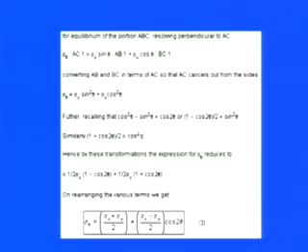Now, within the equilibrium of the triangular part ABC, if we resolve these forces, first we have sigma theta into AC, where AC is the inclined part. So sigma theta into AC into unit depth, that is 1, equals sigma y sin theta into AB into 1, plus sigma x cos theta into BC into 1. Converting AB and BC in terms of AC, AC cancels out from this side, so we can resolve those forces.